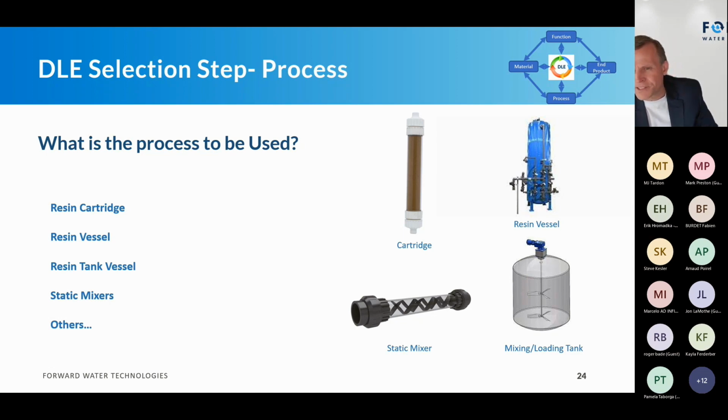Standard Lithium, this is kind of what they're using in their process, where the resin is in the tank, they load the brine, mix it up, and then pump the fluidized slurry over to another vessel to be eluted. So when you're looking at your DLE process, the other question is how the brine is going to be loaded onto the material.